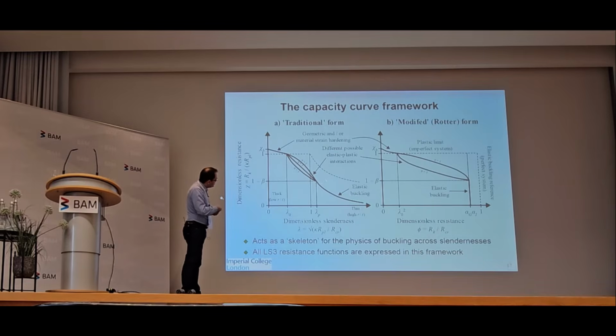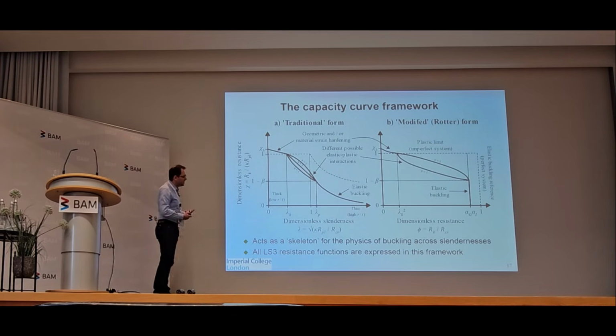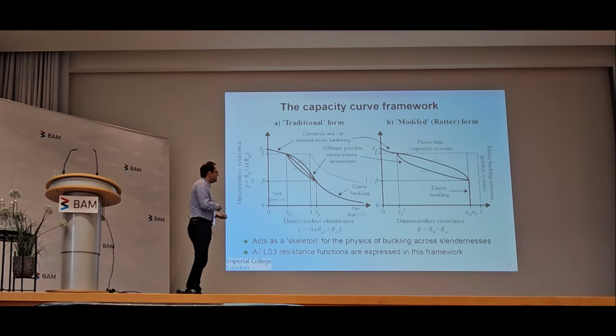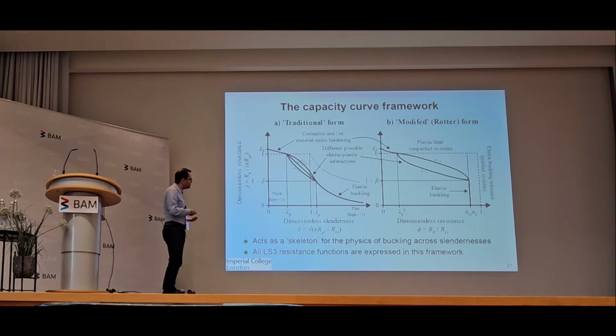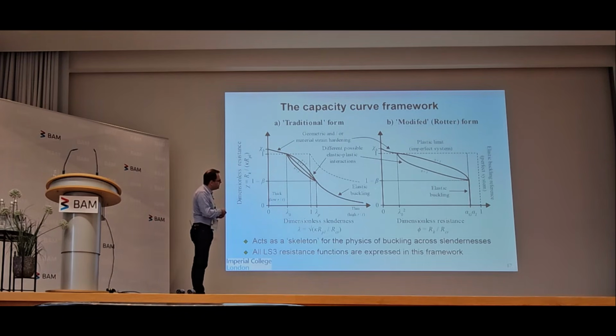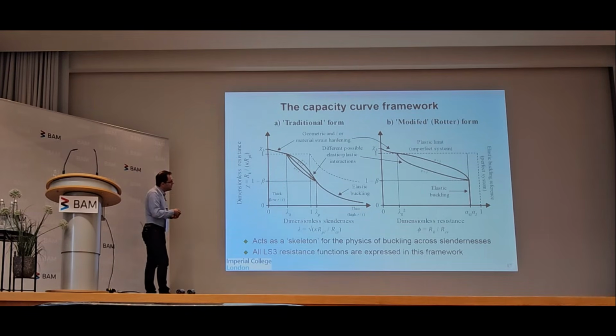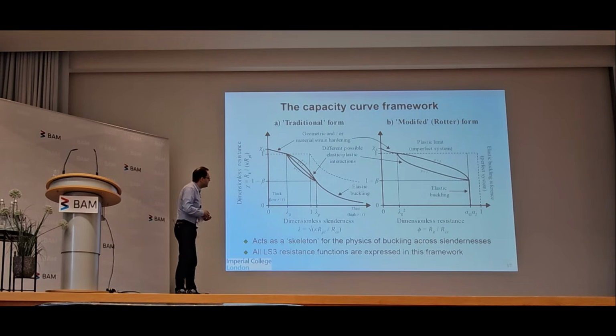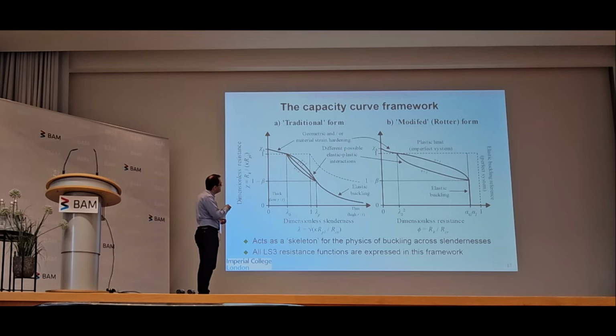Going up the curve this way, here is where you have elastic-plastic buckling, and there are different aspects of the physics there, and they're captured using different parameters. So you have a beta parameter that identifies where plasticity first begins to influence the relationship, and then the shape of the relationship itself, the severity of the elastic-plastic interaction, is captured with the eta parameter.